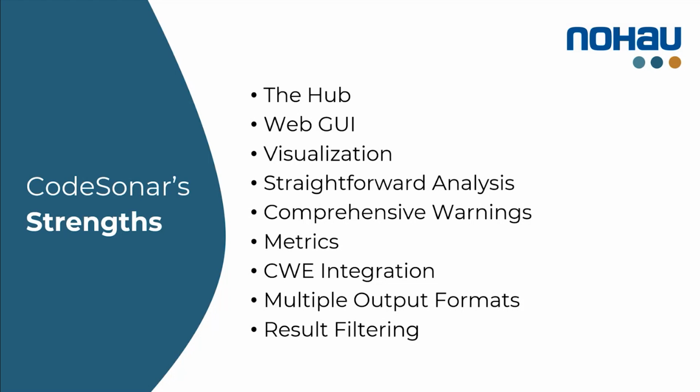Metrics: by default, there are some basic metrics that are calculated, but you can also use standard metrics like HIS, and CWE integration, of course, for security. And then if you're not comfortable using CodeSonar as is, there are multiple ways that you can interact with other third-party pieces of software because you can export in different formats, and you can filter all your results. So it's very simple, and we're going to look at the interface in a second.